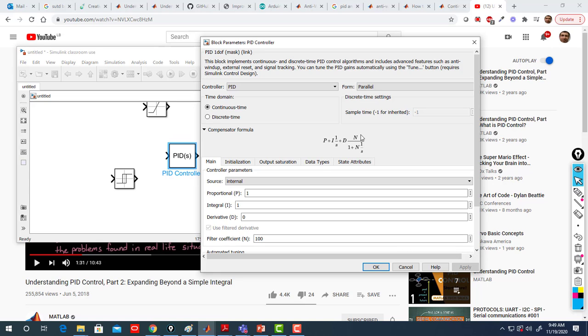So in practice, why are we not taking the saturation effect into account? Here the PID block doesn't consider the wind-up effect, just the noise. Well, there is a reason. First, we cannot realize KD s, or D times s alone, so we integrate it here. However, I over s is realizable, because the degree of the denominator is more than the degree of the numerator. But that's not the case if I want D times s alone. That's why you are seeing it here.